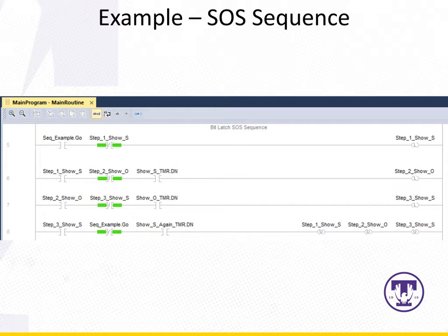That's powerful because now we don't have to put comments for every single rung and explain what each of these tags does. If we did that, what you would begin to have is overload, and there would be so many comments you wouldn't consider any of them important, and you would ignore all of them. So too many rung comments is a bad thing. Instead, use rung comments sparingly and to help provide commentary on the order that you have and the structure that you have. For additional commenting, use tag names.